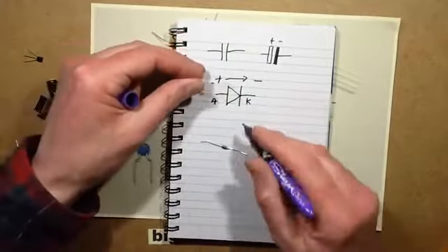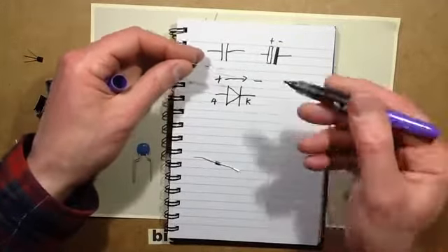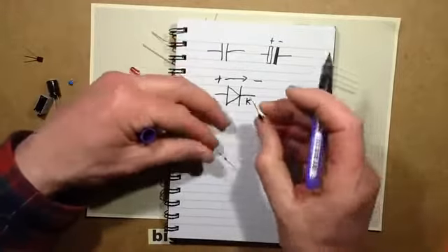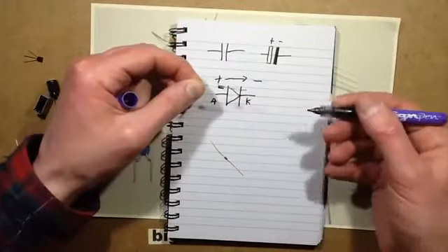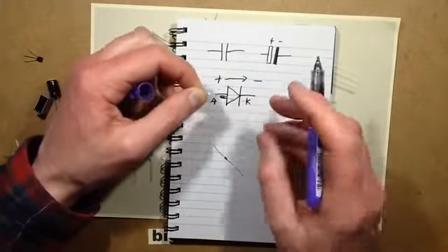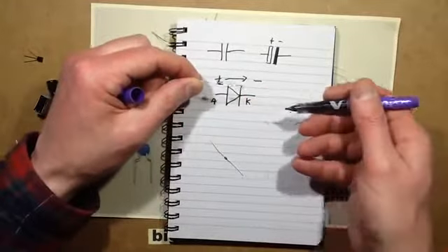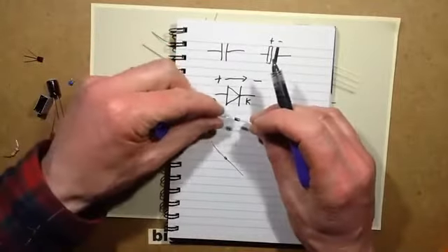And the other factor is the peak inverse voltage. That's what voltage it will block coming in the wrong direction. So supposing, well, this one is a 1N4007, it's rated 1000 volts. So that means that it will block 1000 volts going the wrong direction. But if you were to exceed that dramatically, it will avalanche and it will start conducting in the opposite direction. So you have to choose the correct diode for the job.